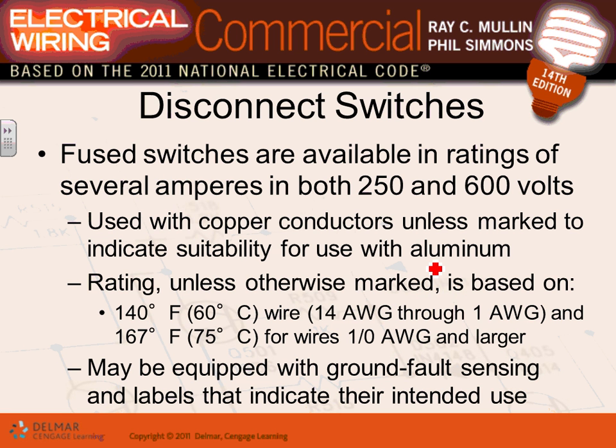The switches and the fuses that go with them. Most of what they're going to be dealing with is rated for either 250 or 600. If it's 600, guys, you're looking at a 480 or 600 volt system, 3-phase or single phase. This one, you're looking at 208 or 240, single phase or 3-phase, where you can apply these switches.